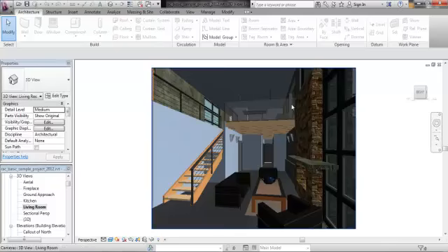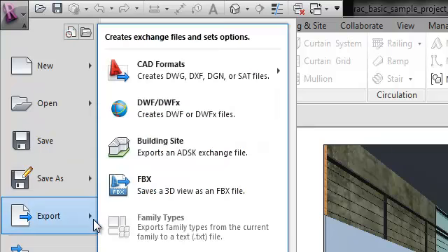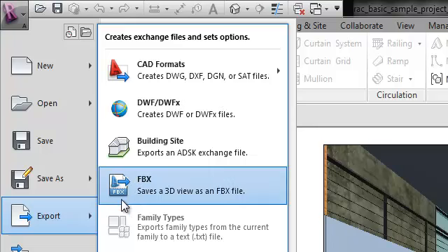By saving it as a .dxf and bringing that file into Maxwell, our already set camera will be lost and the model comes in as an exterior perspective only. Since we want our workflow to be practical, it is much more advantageous to save our Revit file in a way that includes our camera angle, specifically for our interior shots. So I will now export this model as a .fbx file so that I can import it into software that will read our camera angle, which is 3ds Max.